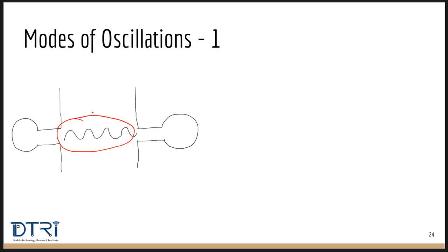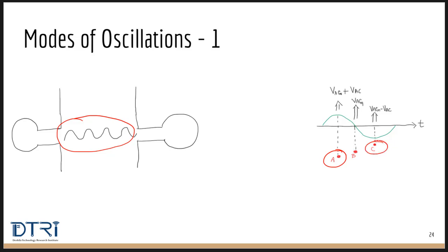Let us consider multiple cycles of sine waves as shown here. In practical klystrons, it takes more than one cycle to create a bunching effect. Consider the same example of three electrons. While electrons A and C experience accelerating and retarding voltages respectively, electron B did not encounter any extra voltage from the cavity. So this electron is considered as our reference electron.